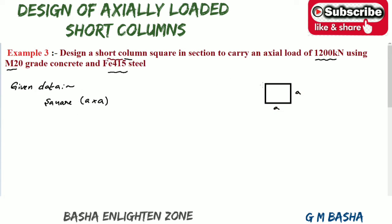And axial load is given: load equal to 1200 kilonewton. M20 grade concrete means fck equal to 20 Newton per mm square, which is the characteristic compressive strength of the concrete. Fe415 steel means fy equal to 415 Newton per mm square. So all these are the given data. For this data, you have to find the square column and then follow with the design.